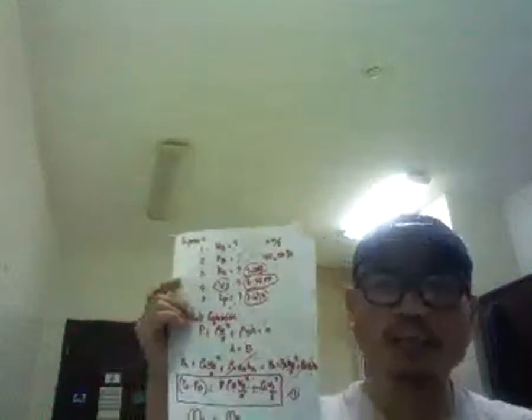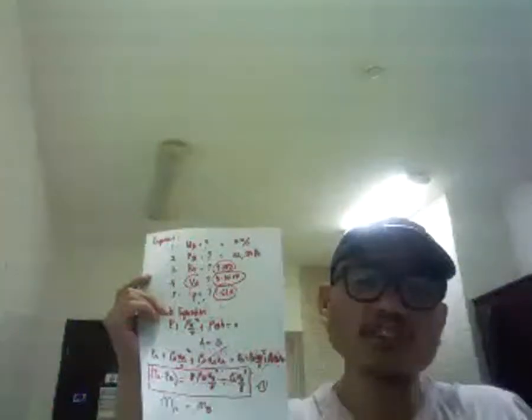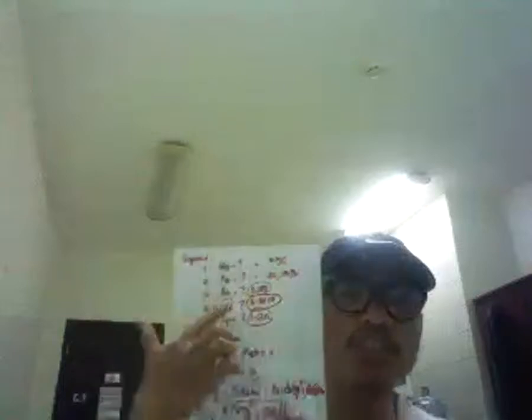Okay, we have no more time to investigate, so we will investigate it later. It will just be simple. Last, using Reynolds number, we prove that the Reynolds number must be less than 2,100 for the flow to be laminar and for the Bernoulli theorem to apply. Based on our solution, we obtained 3,000, which is the transition stage. Okay?